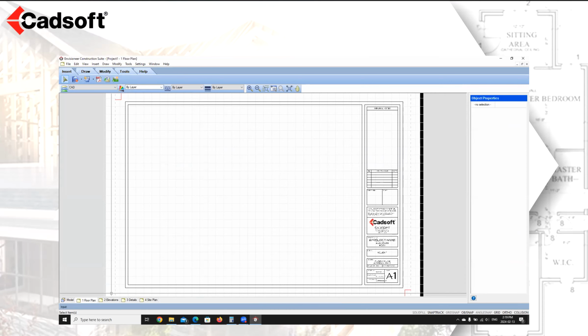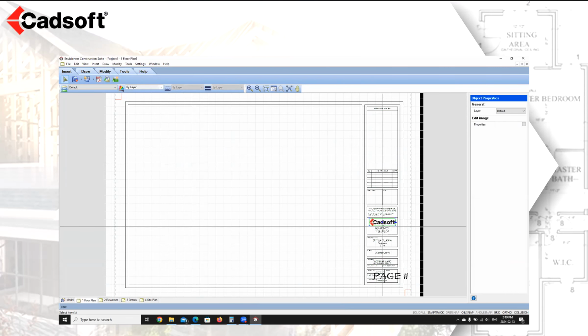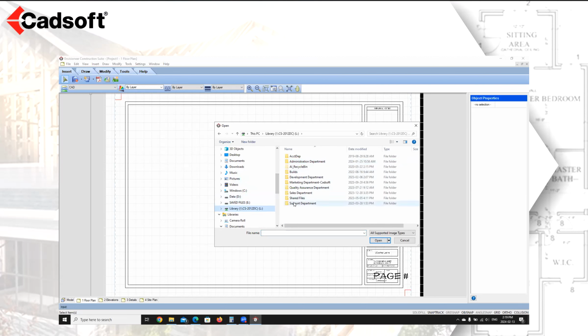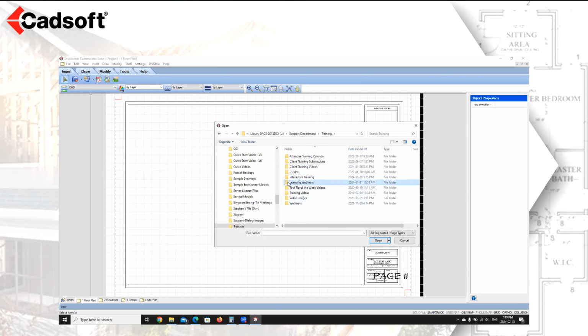In last week's webinar, we actually went through and we looked at how to create our own custom title blocks. So I'm just going to quickly go in. I'm going to select this title block. I'm going to go in and say edit. I'm going to delete out this and this and this. And then I'm going to insert a new image. And I'm going to insert an image from library. And we're going to go into, I have that saved in here. And we're going to go up to training and webinars.